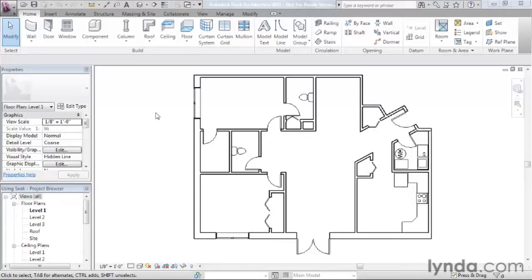Fortunately, alternatives do exist. There are many websites available that offer Revit content for download, and many such items are free of charge. The most accessible choice is Autodesk's own Seek website, available directly from within the Revit software. All we have to do is go to the Insert tab and type in a search in the field, and we're taken directly to Seek and presented with the results of our query. So let's go ahead and give it a look.